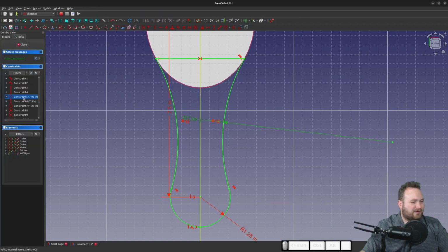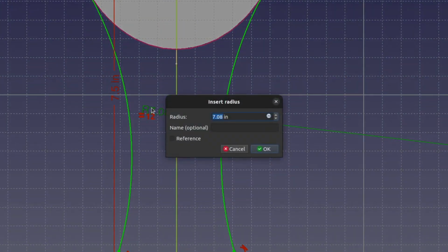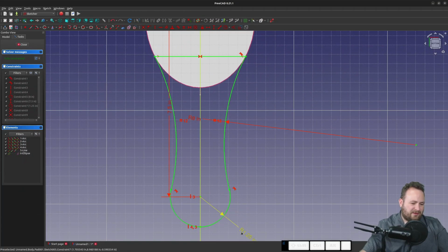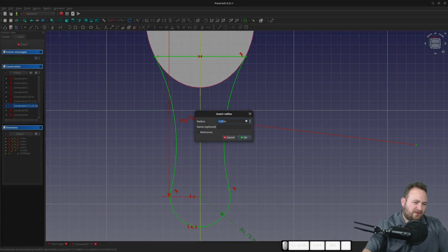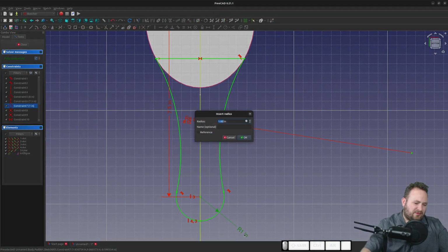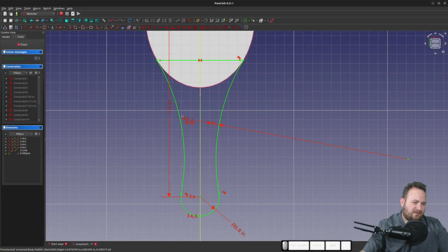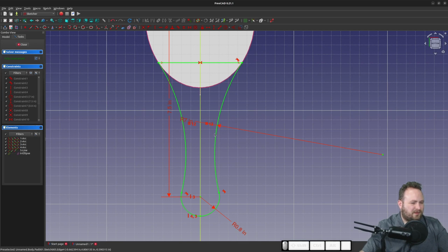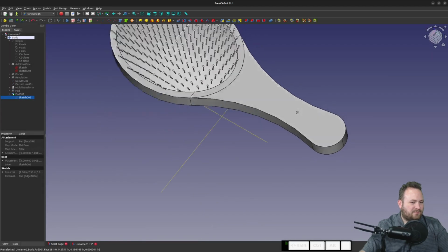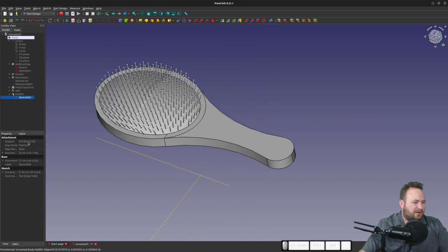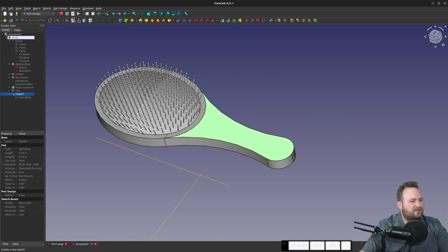So we'll double click Sketch 005, and I think I can change this geometry to maybe 8 radius, and then we'll take this down to 0.8. Maybe I'll make that 7. Close that. Yeah, not too bad. All right, so what do we want to do now? Maybe sketch on this face.